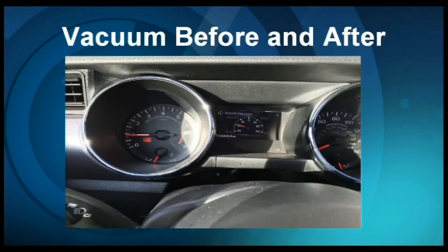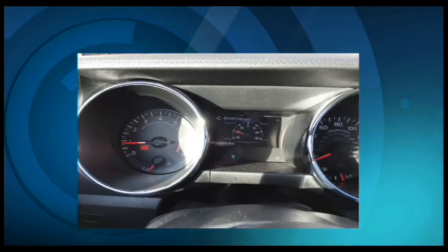So there you can see the 18 inches, and after the cleaning, just a hair over 20 inches of vacuum, showing you that you have improved the induction system and the flow of air to the engine by doing a cleaning of the upper intake, the combustion chamber, spark plugs, oxygen sensor, the back of the valves, and possibly even the catalytic converter.